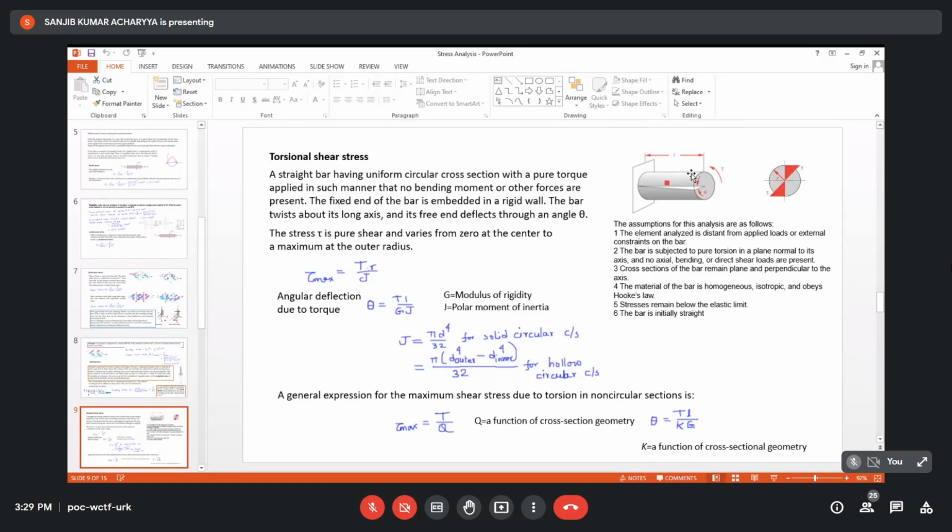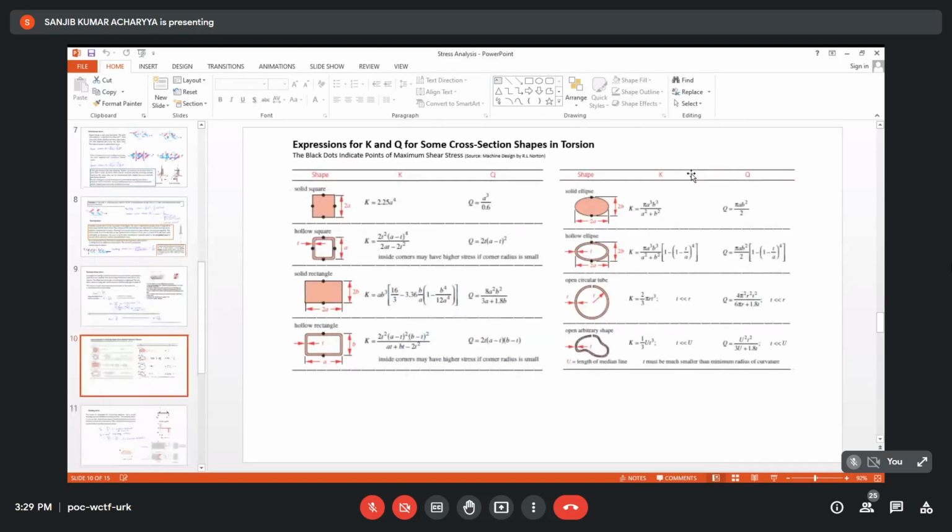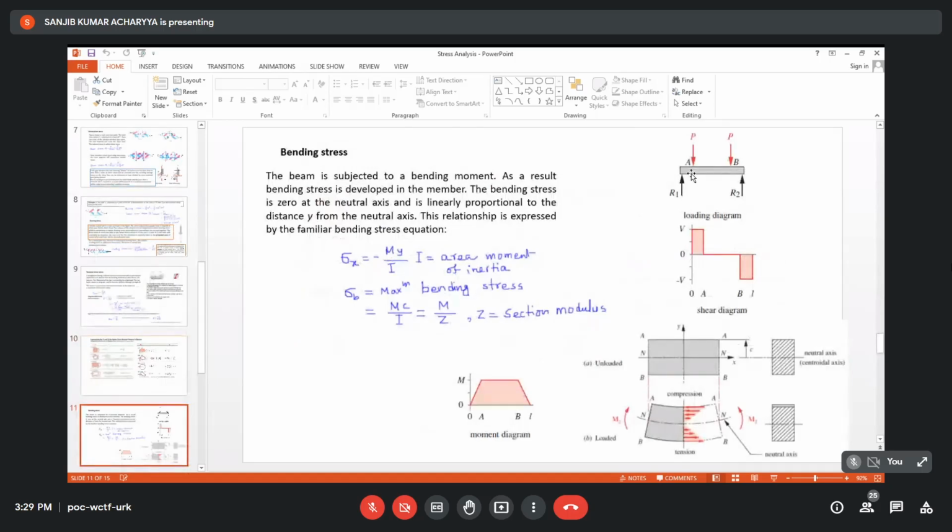Yes, sir. Now another thing can happen, bending stress. Have you studied this? Yes, sir, mainly. Depending on the bending, one half remains in contraction and the other half in tension about the neutral axis, half tensile, half compression. On the surface, one extreme has maximum tension and the other, 180 degrees apart, has maximum compression.